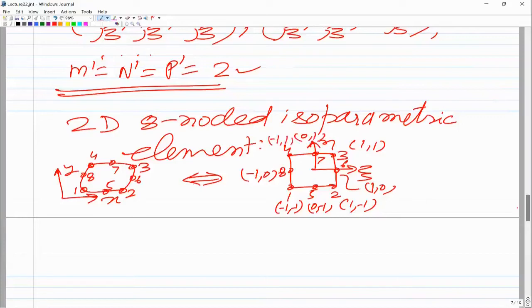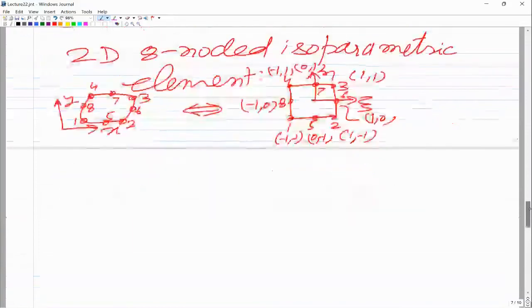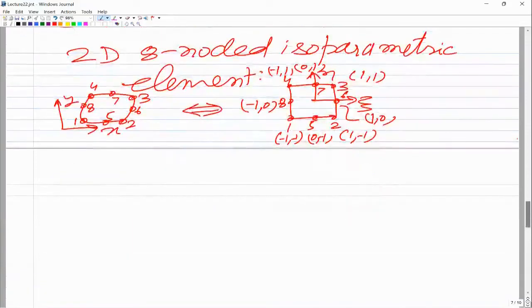If we are solving a temperature problem, then we will assume an approximate solution for temperature. If we are solving plane stress, plane strain, or axisymmetric problems, then we will assume an approximate solution for u, v and w. Suppose I take the variable u. At each node we have primary variables u, v and w as degrees of freedom, so u would be written as an 8-term polynomial.